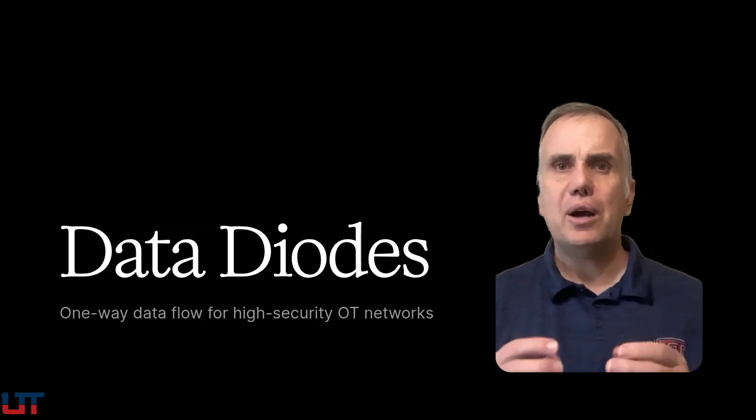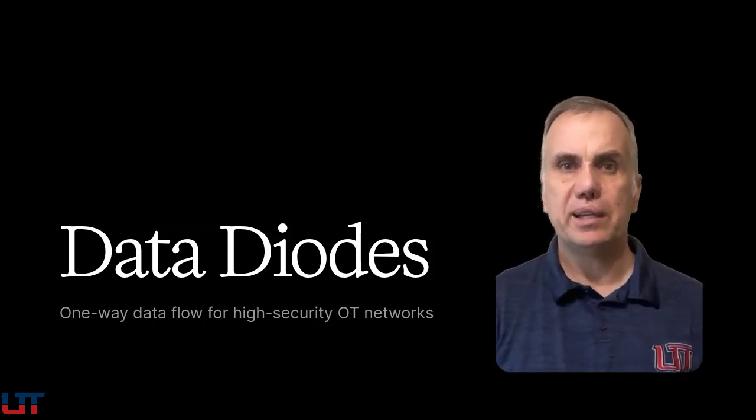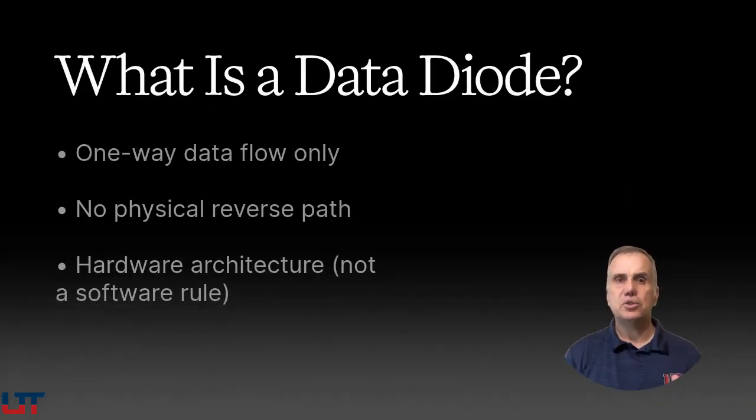How do you allow data to flow out of an OT network while making it physically impossible for anything to flow back in? A data diode is a hardware device that allows data to travel only in one direction. The reverse path doesn't exist at the physical level. It's not a software rule that blocks return traffic. It's a hardware architecture where a signal physically cannot propagate backward through the device.